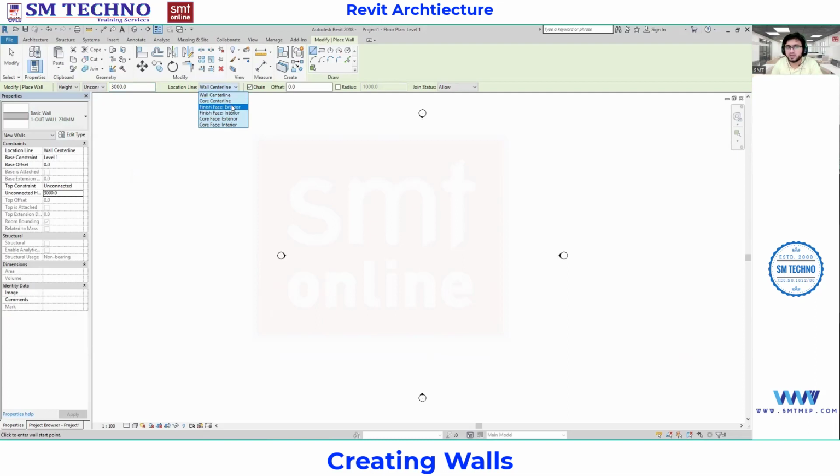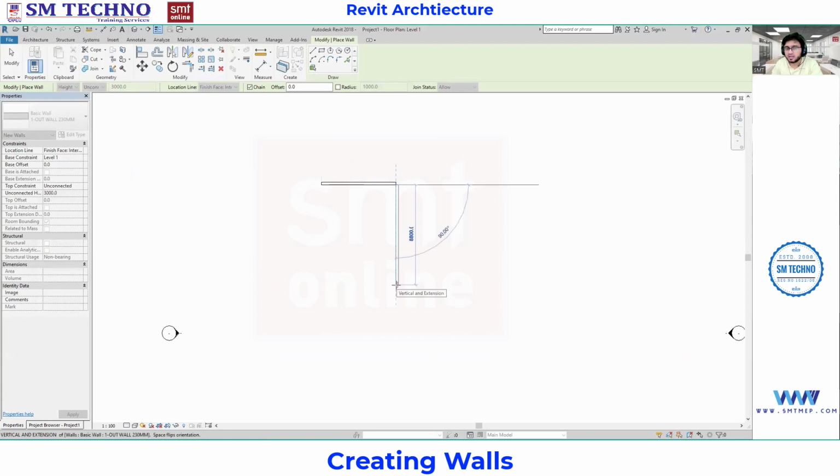Now in the options bar, from which point you want to draw? In the finish face, interior, exterior, whichever you want. And with finish face, interior. So now draw the wall. I'm going to draw a wall of 6,600. Again, you can see something like 8,800. So in this way, you can select.